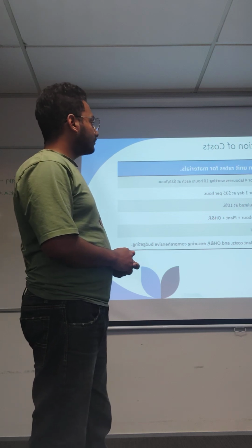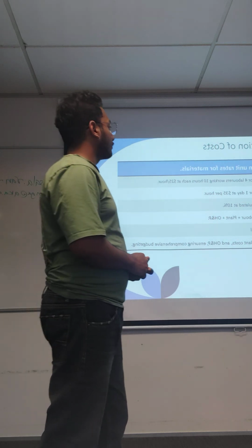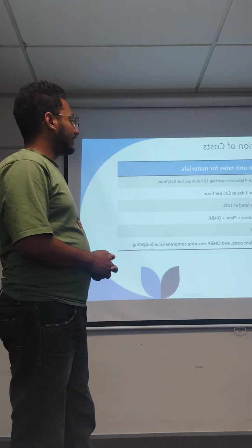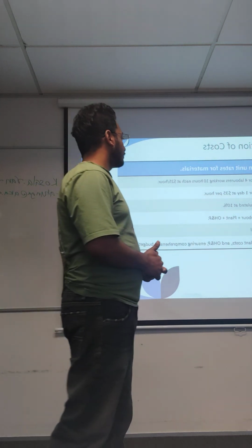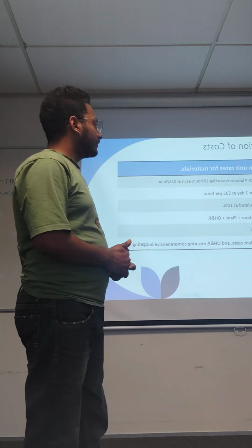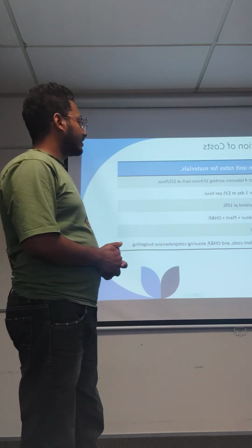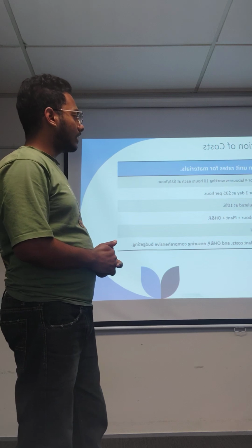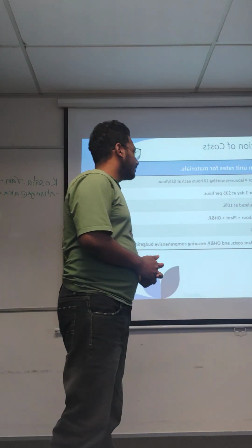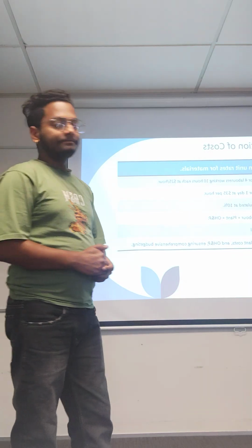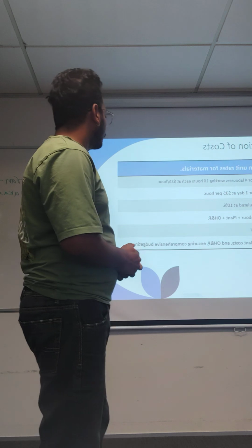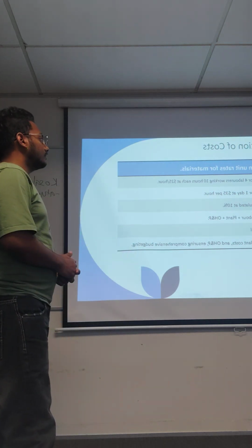Overhead and profit is typically calculated at 10%. Total cost is material plus labor plus plant plus overhead and profits, and the wastage is 5% of the material. Total costs are derived from adding materials, labor, plant cost and overhead and profits, ensuring comprehensive budgeting. Next one.